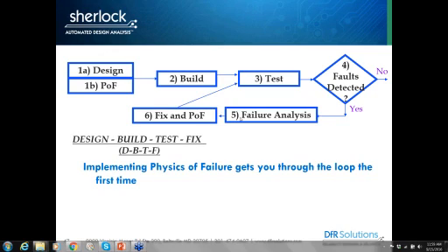But right now we can't say, hey, I want to automatically vary the solder stencil thickness from 4 mil stencil to 8 mil stencil and look at the time to failure changes for all my parts. We haven't done that yet. It is something we are looking at doing, this sensitivity analysis for DOE.